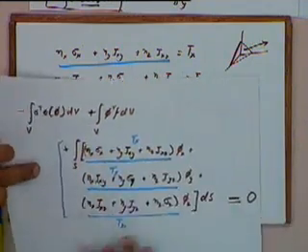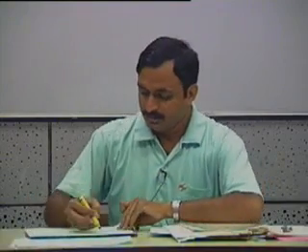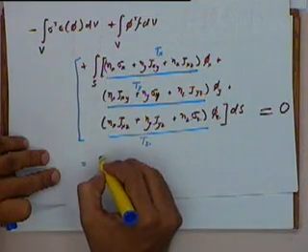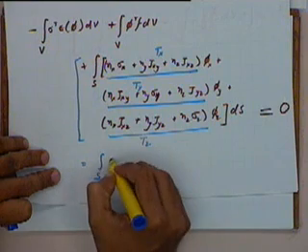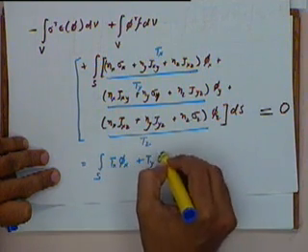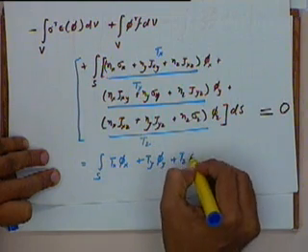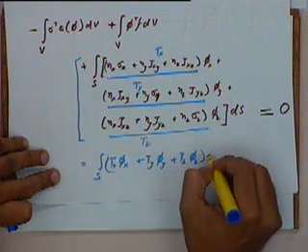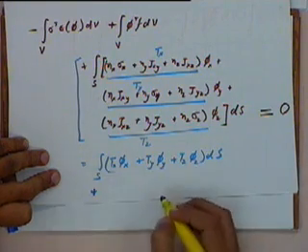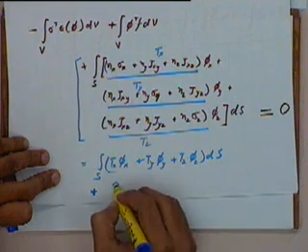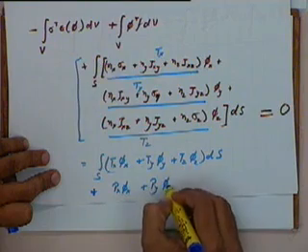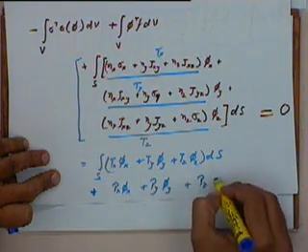So this surface integral will be equal to the surface integral of Tx phi x plus Ty phi y plus Tz phi z multiplied by dS, plus for the point loads Px multiplied by phi x plus Py multiplied by phi y plus Pz multiplied by phi z.